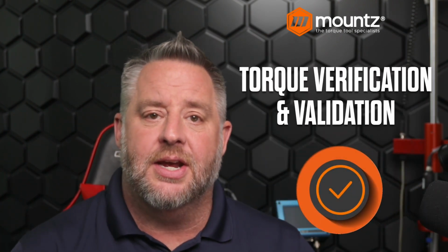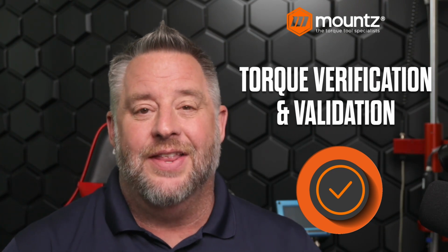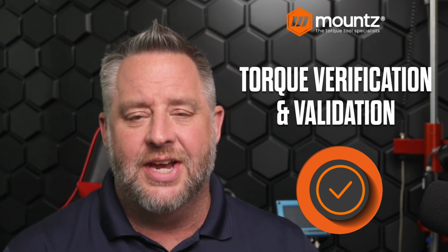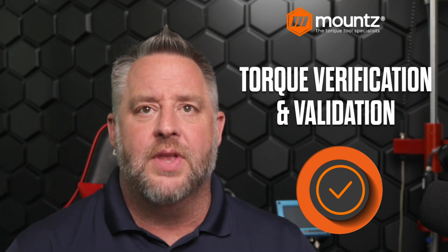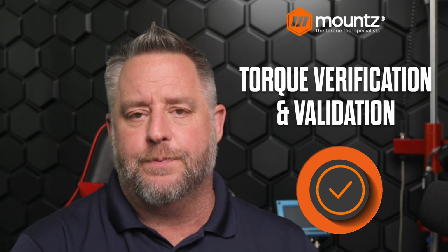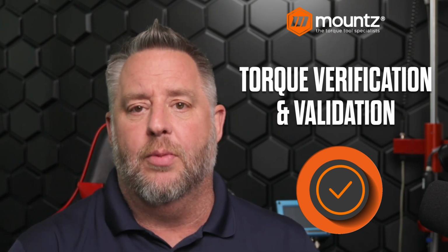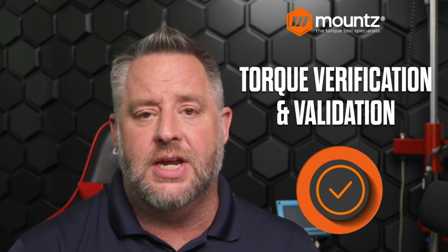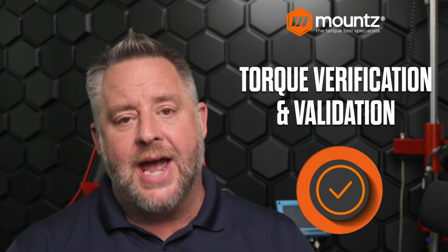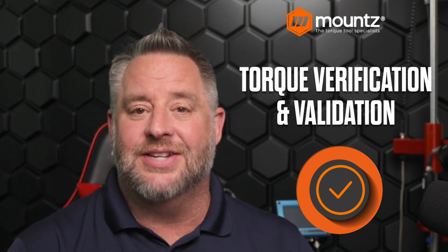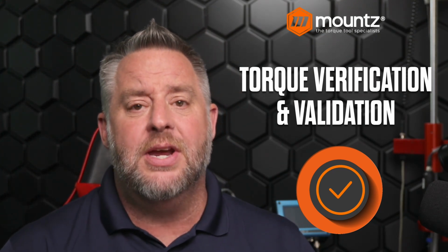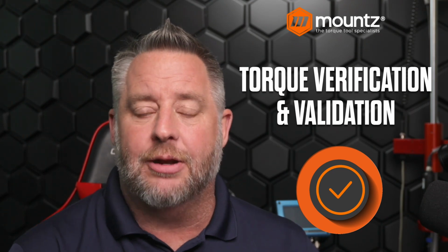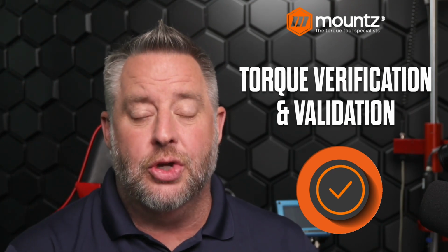So next is going to be, basically, during the assembly process, and this can be used for the torque verification and torque validation process. And this is very, very important, because if you're sending your tools out on an annual basis or some type of predetermined time basis for your tools to be calibrated, if that tool comes back and the as-found reading is outside of the tolerance, that can be a real issue, because you really have no idea at what point did that tool go out of calibration, what parts may have been used on that particular tool.